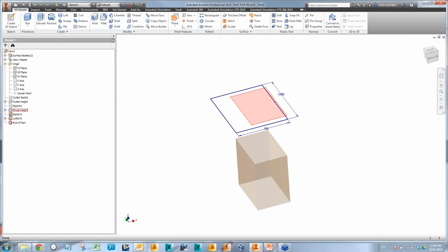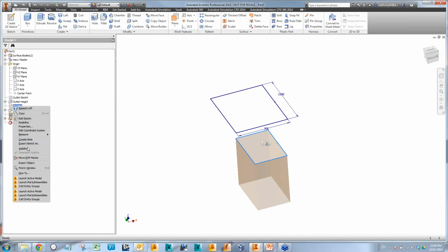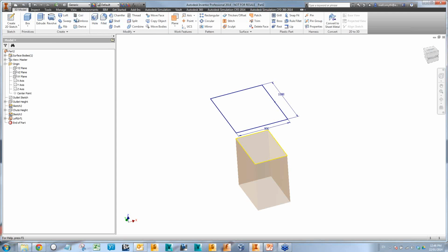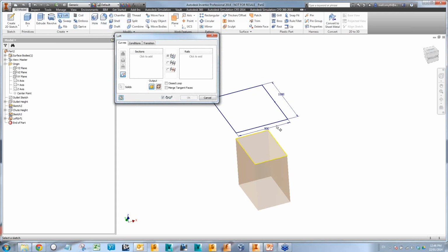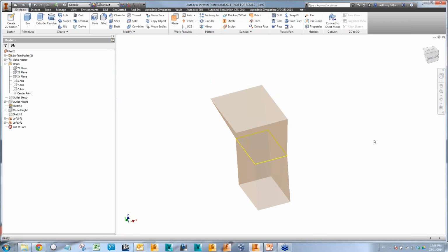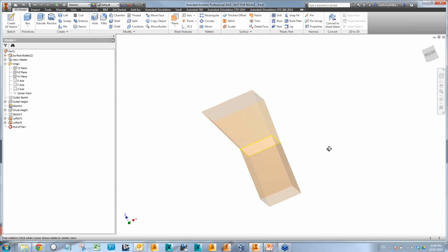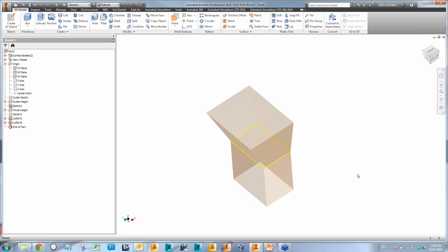Click OK. And I'm going to make my sketch 2 visible again, so I can continue and make another loft from the top sketch. Again, it's going to be a surface loft. Top sketch, and I thought I had to join the dots, but I picked up the loop there nicely and click OK. So what I've got now is a surface. Okay, and this surface will allow me to position sketches nicely when I start deriving this part into other parts